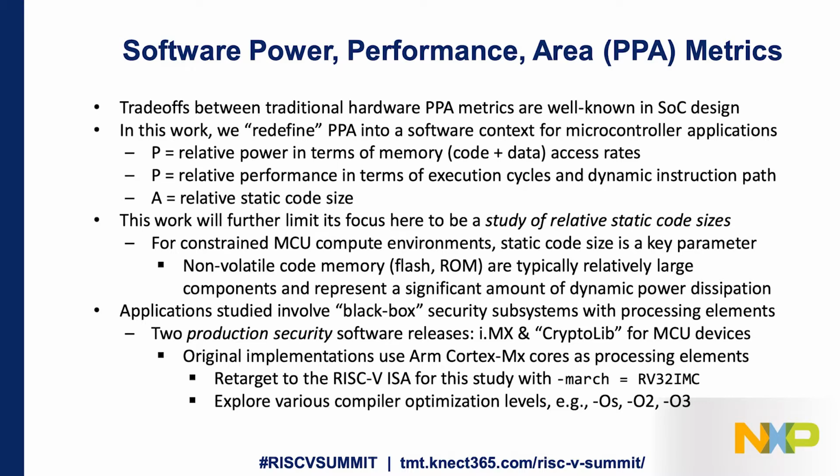That's because typically non-volatile or ROM storage areas tend to be relatively large components on the device, and they also consume a relatively high portion of the active power. So optimizing for minimization of those hardware components is a very key parameter in the overall SoC design.